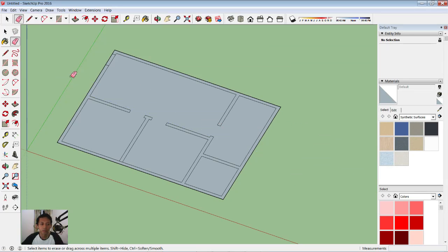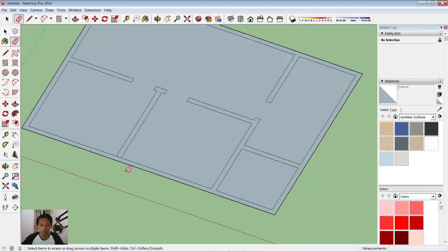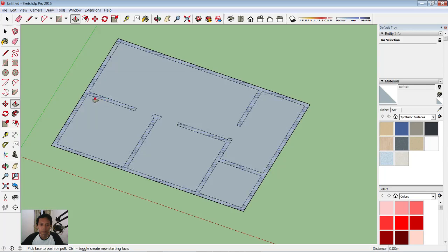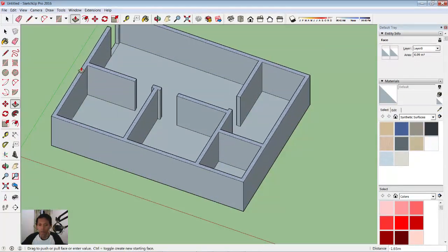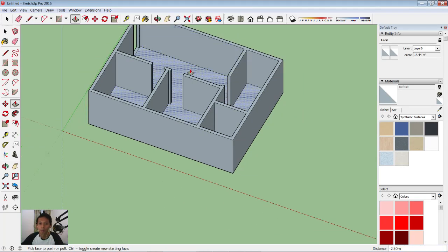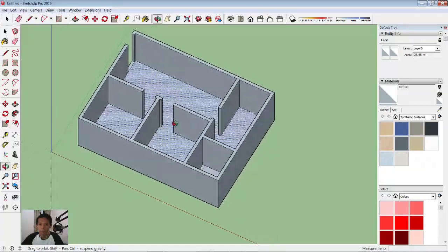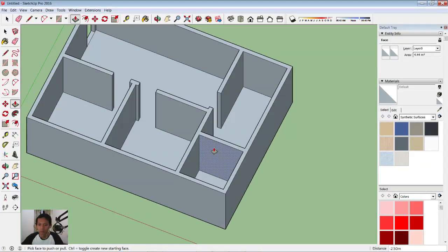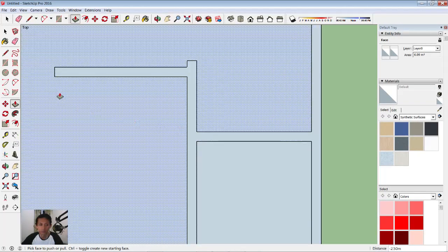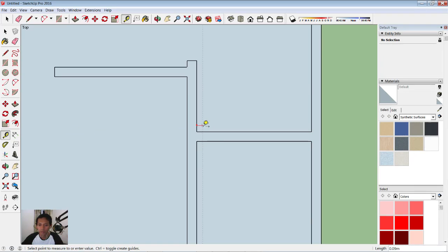Next you can use the extrude command to extrude this wall. Okay, I will erase this line first and then we extrude to the top here about 2.5. Okay, next we create a door in here. Okay, I will use tape measure 0.1 and then 0.7.